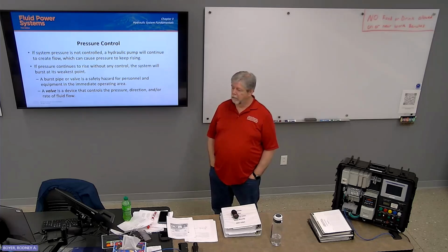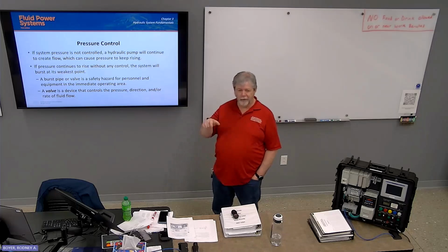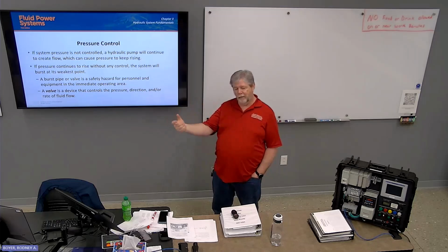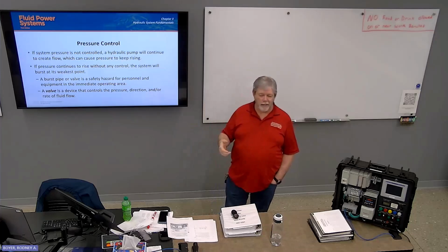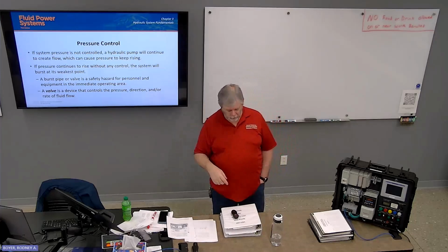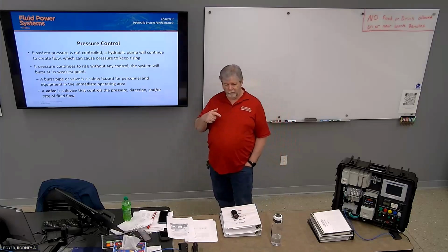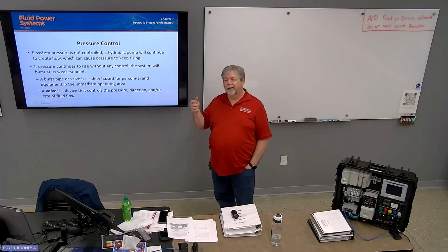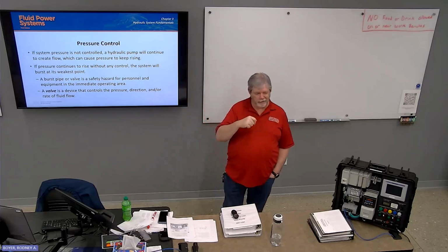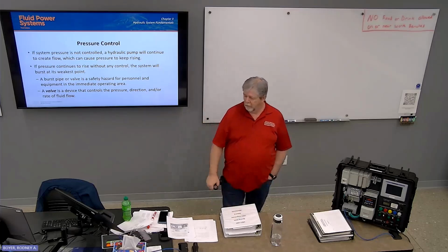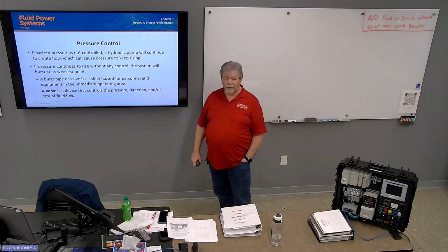Okay? We want our system to run at a given pressure, so we set the pressure relief valve at that pressure. And no matter how hard the pump tries, it cannot exceed that. Problem is, the pump is going to continue to produce as much as it can, which is going to force the relief valve open, another source of friction, another way to raise the heat of the system. But that's better than things blowing up.